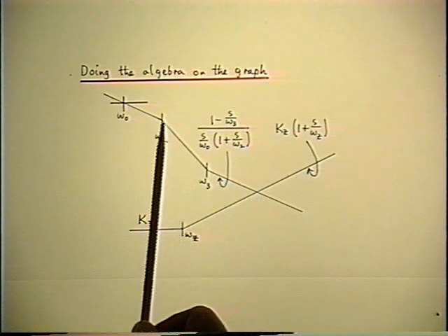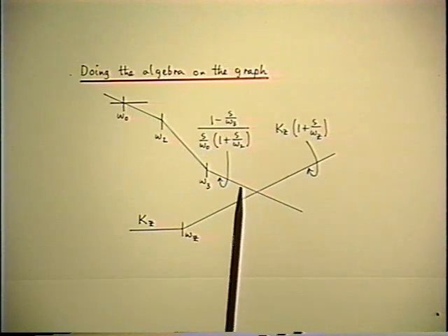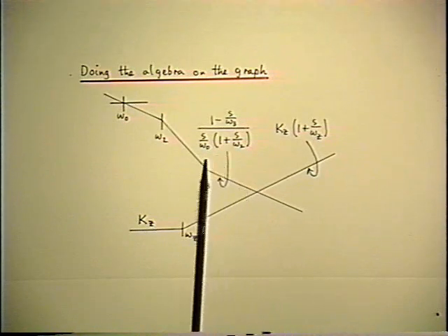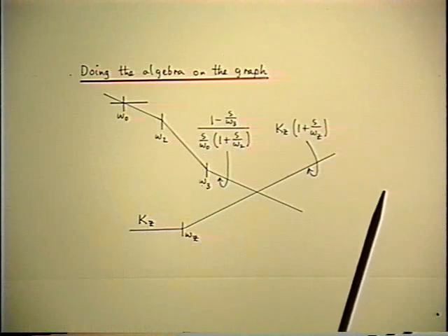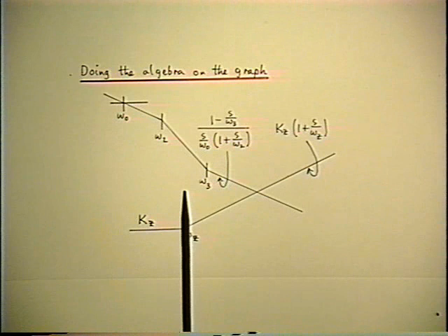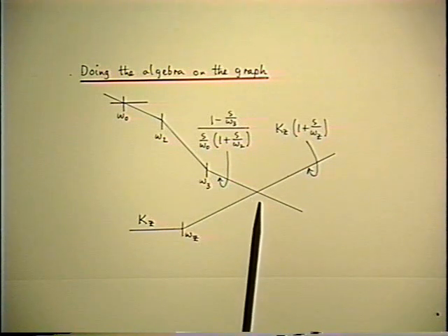Because obviously these corner frequencies down here have nothing to do with what happens in the region of transition. So why not throw those frequencies away? They're not important in determining the only unknown part of the solution.